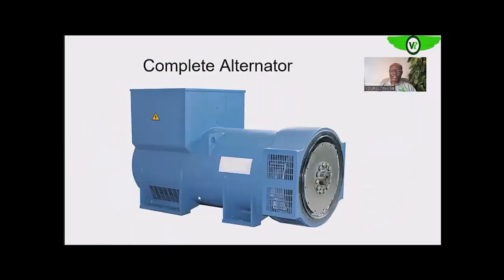So here we can see a coupled alternator. So we have the field winding, this is a complete alternator. This plate is what is coupled to the flywheel if it is a diesel-driven engine, or gas-driven engine, or steam turbine, or what have you. If it's a steam turbine, here is coupled to the shaft that comes out of your gearbox. If it's a gas turbine, the same thing.